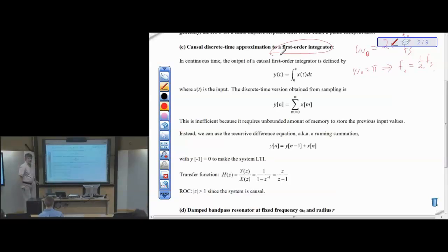So in continuous time, this is a building block in integrated circuit design, electronics. And it's also very useful to us in discrete time. So here it is. The integrator is simply integrating the input over the previous times that I've seen the input value. And there's an initial condition in here that needs to be 0 if this is an LTI filter. And the same was true with part B. There was one initial condition, which was the previous input value. That has to be 0 for LTI.